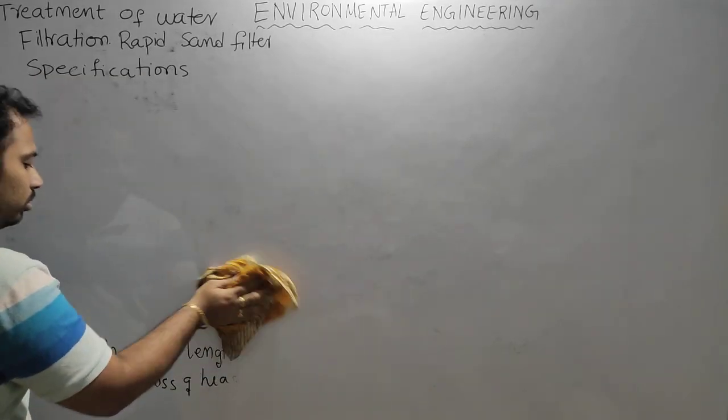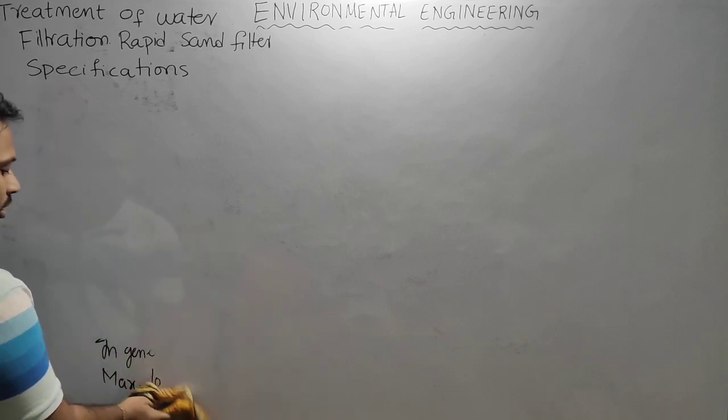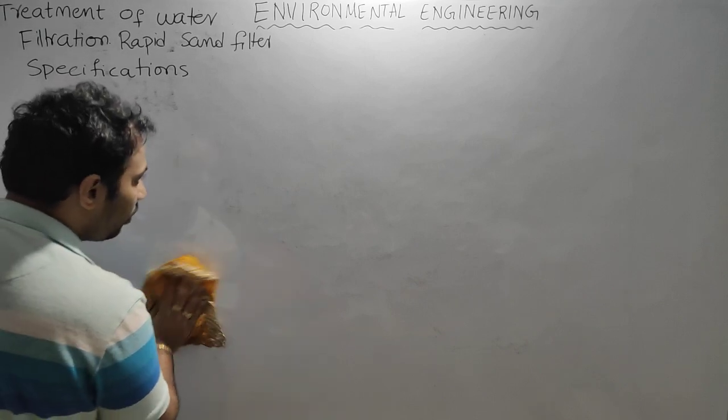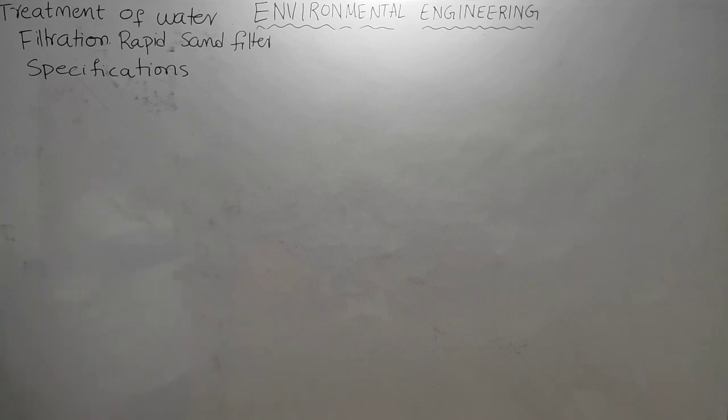The rest of the time we do normal filtering, and for this 10 minutes we send the water through the bottom under drainage unit with a high amount of pressure and velocity.